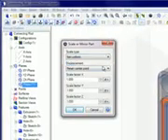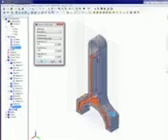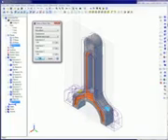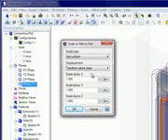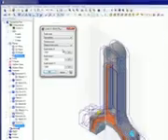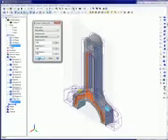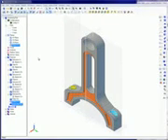The non-uniform scale option allows you to distort the resultant part in the X, Y, or Z direction. Here the transformation is executing about the origin, changing only the x-axis to 1.5. Here's the exact same transformation, except this time the transformation is about the part center point. There is no apparent difference between this transformation and the last one because the part is centered on the origin.